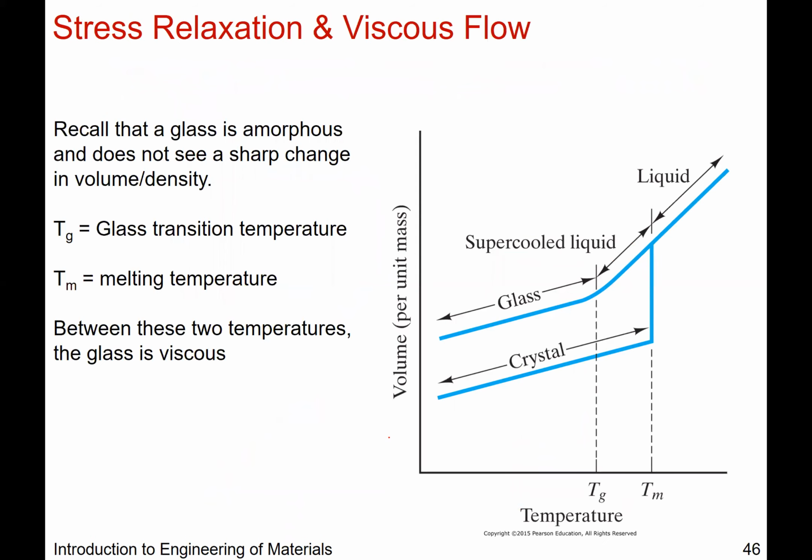So what's happening in these polymers is that in terms of the change in the volume of the material, unlike metals, where upon melting you have some volume that's in the liquid state, and then at the melting point there's a drastic change, right? And then you have crystallization and there's some volume change there, but it's quite dramatic, the change in the volume for, let's say, a crystal.